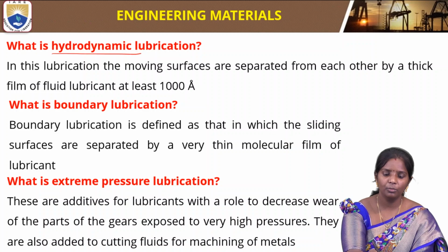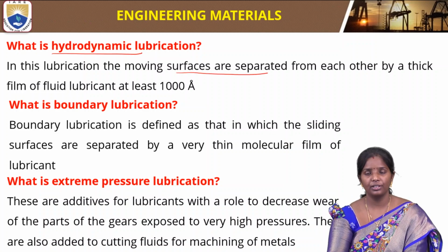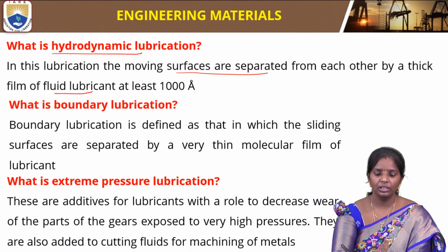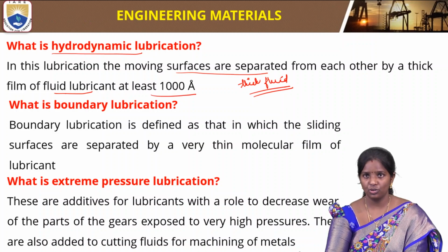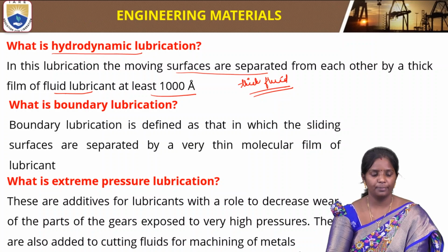Next, in lubrication we have different types. Hydrodynamic lubrication: in this lubrication, the moving surfaces are separated from each other by a thick film of fluid. A thick fluid is applied, with a thickness of at least 1000 angstroms.